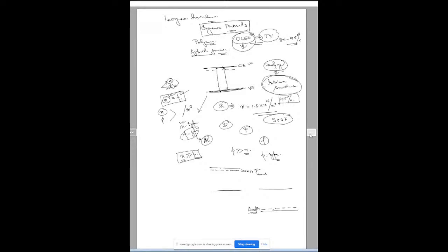So in a semiconductor now, you have thermally generated carriers coming in. If you have a doped material, then in the conduction band you have some electrons already present, and some holes will be there. If you are considering an n-type material, normally we consider the concentration in equilibrium, so we call it n0, the equilibrium concentration.